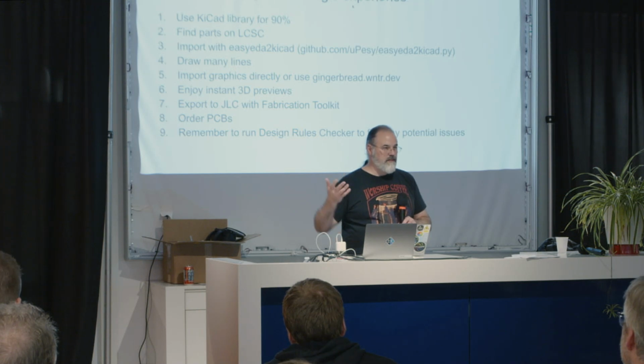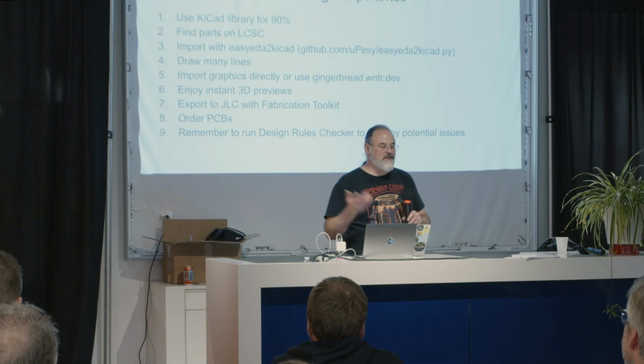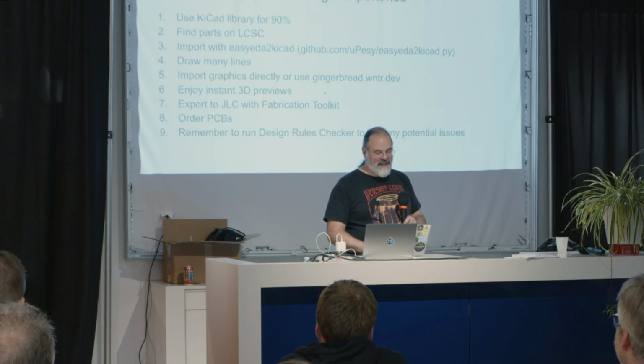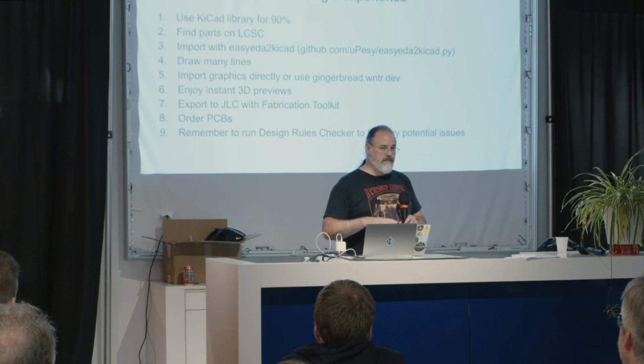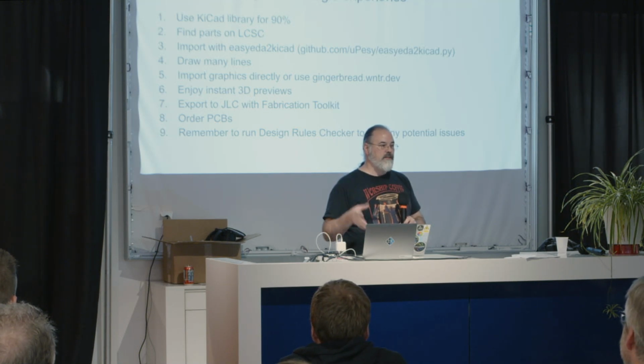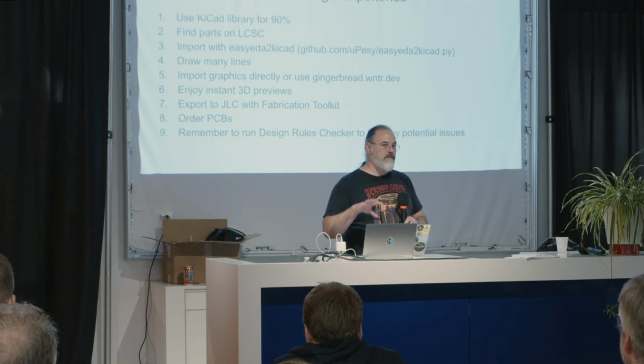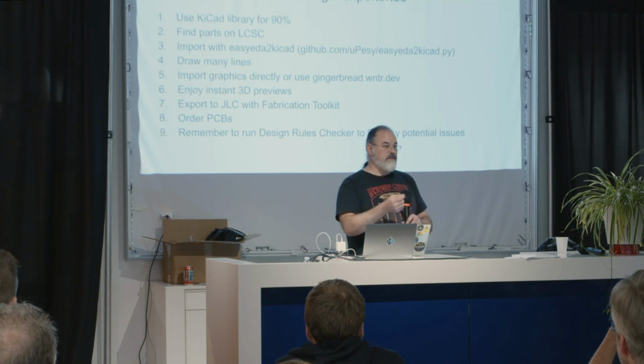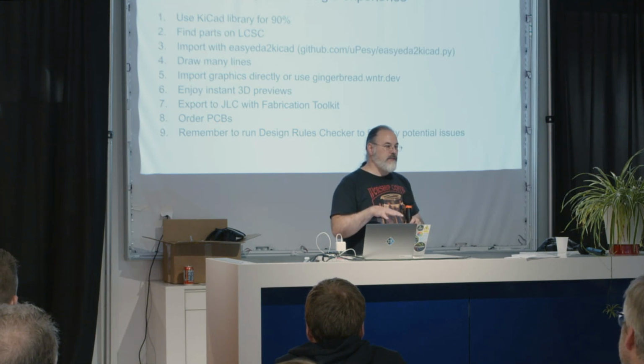Right, so that's step 3, get all the parts I need in there, and of course laying out schematics and PCBs, just drawing lines, really. Many lines, but just drawing lines. And then for graphics, I'm using a tool called Gingerbread, made by Thea Flowers. It's an amazing tool. KiCad has awesome native SVG import, so you can drop an SVG right in there. For super complicated SVGs, it is almost too faithful to all the different curves that can go on in there. And so if you pull that in and you find it to be slow, give Gingerbread a try.